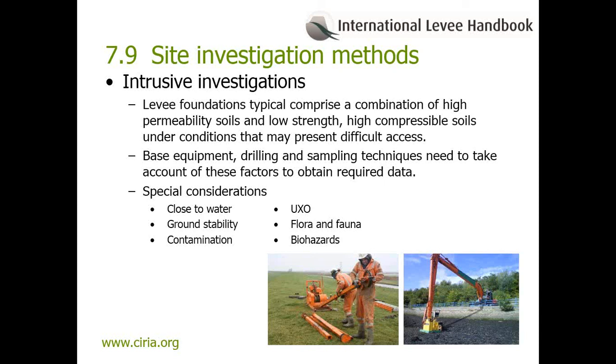While not covered in this presentation, sampling techniques are presented and discussed in a similar format to the intrusive investigations. Specifically, consideration is given to sampling techniques, the quality required to assess particular soil properties, sample size and frequency, and sample handling and transportation.